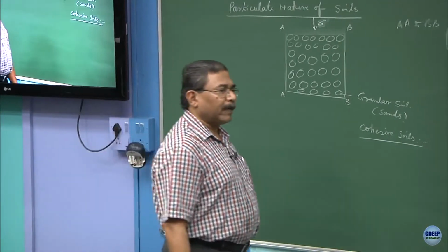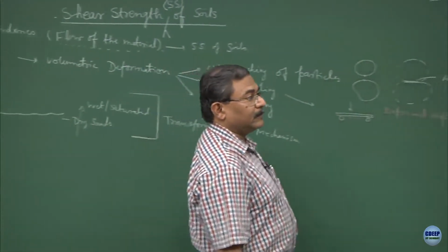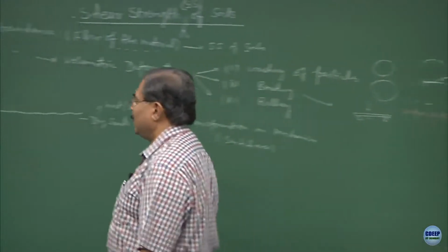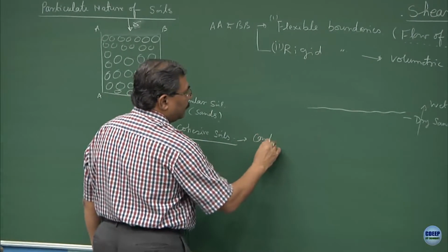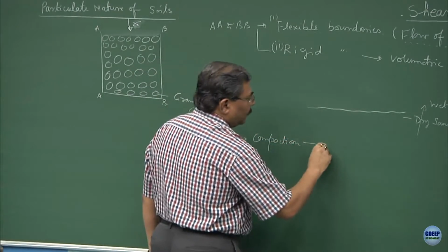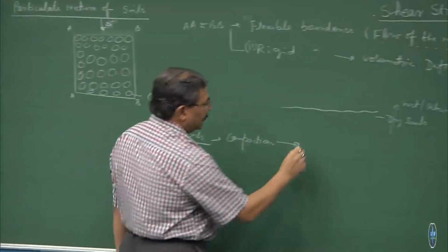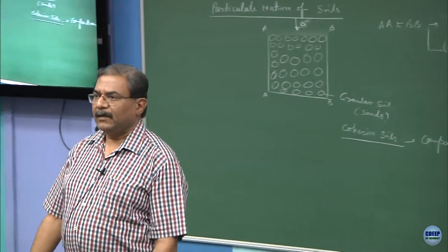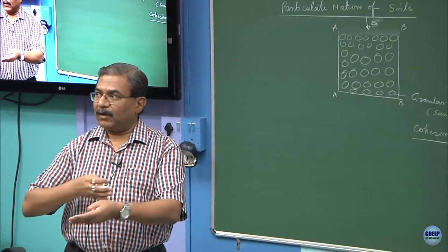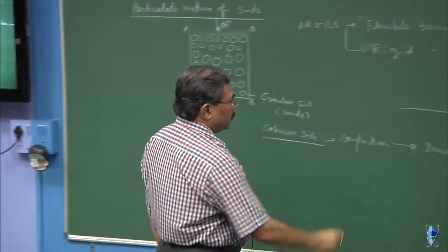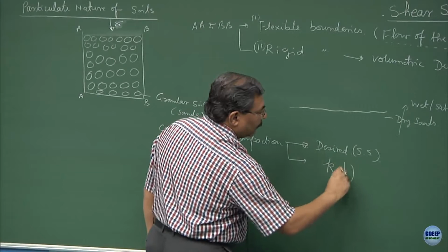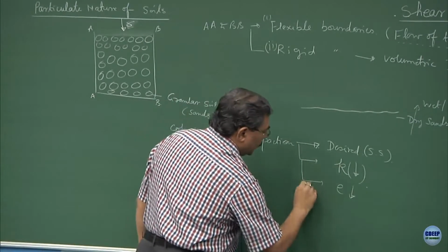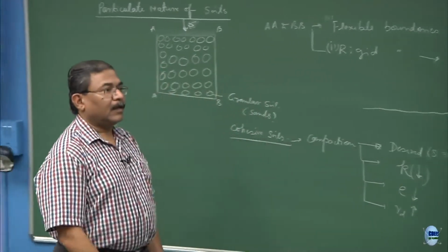And if you remember, the whole idea of compacting the soils was, what was the main objective? To achieve the desired shear strength, correct. So, cohesive soils, when you compacted them, compaction would result in the desired shear strength. What else? I am bringing down the permeability. I do not want water to pass through the systems which I have created. So, this was the K value I would like to decrease. Void ratio decreases, gamma D increases. Clear?